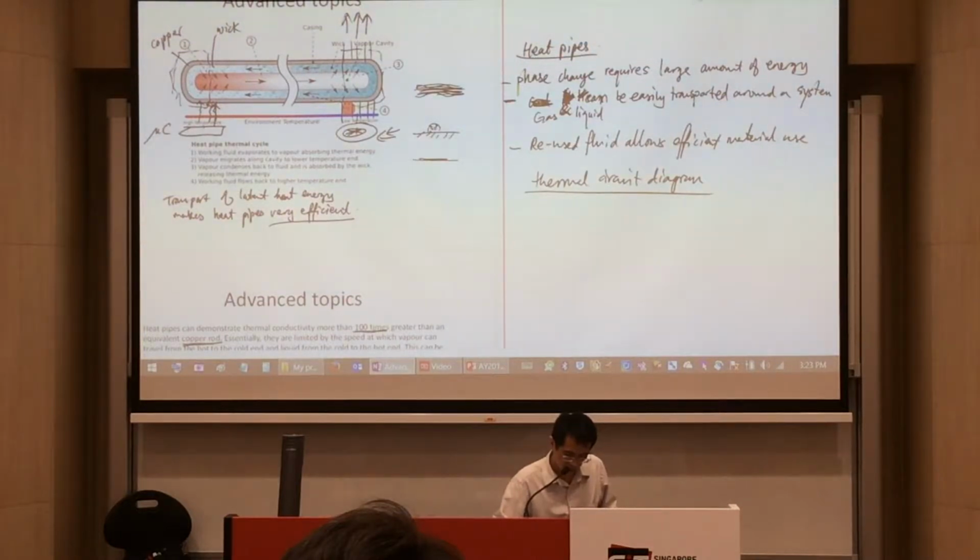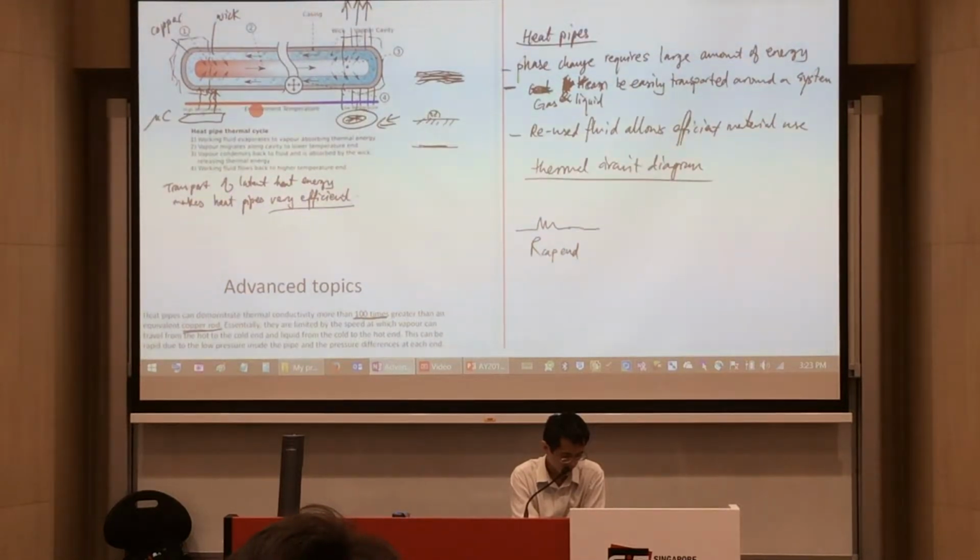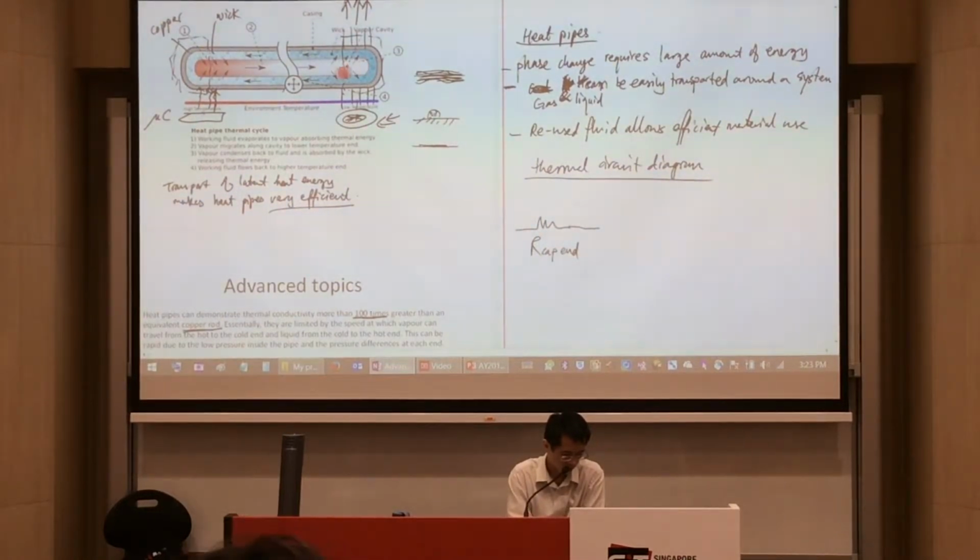You will have a certain resistance for your end cap, and this resistance is going to mostly come from the copper casing over here, as heat gets transferred into it. I want to figure out the entire journey from one side to the other side for this heat transfer. So there's one thermal resistance of the cap end.